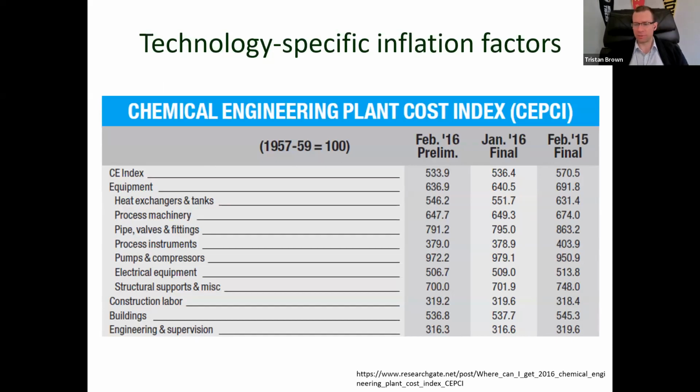Even in the chemical engineering field, right, which is where a lot of bioeconomy systems are going to play in, we see differences, right, depending on the cost of equipment. And so this is something where you can actually go back. There's something called the Chemical Engineering Plant Cost Index. This is a really good way to calculate out the capital costs over years, right, if you're taking a historical estimate. Because what this is ultimately showing, and you can break this down by individual pieces of equipment, just like we're talking about with, say, the module factors, is that there's going to be some years where the equipment gets more expensive. There's going to be other years where the equipment is less expensive. And so, you don't want to necessarily assume, if you have good information, that it's just constantly increasing based on the underlying rate of monetary inflation.